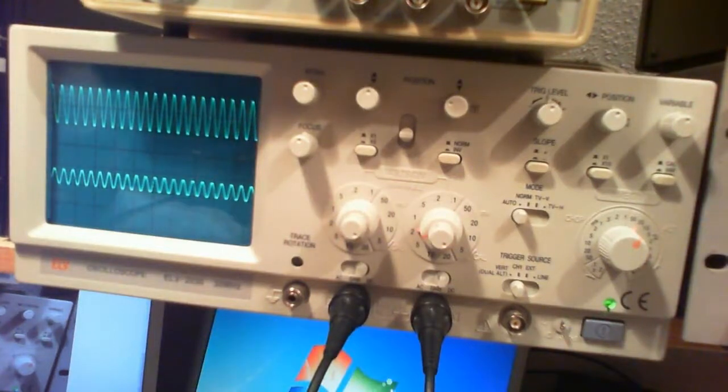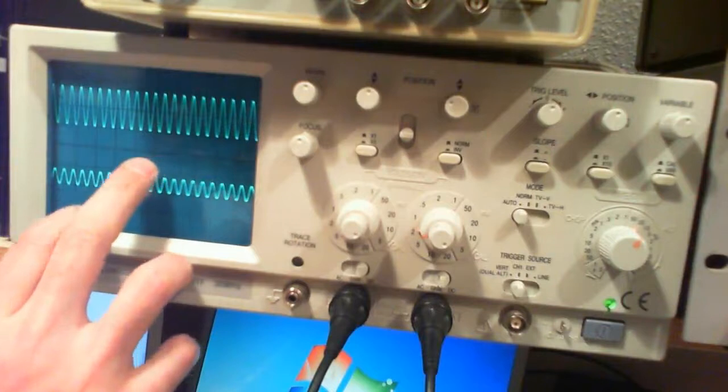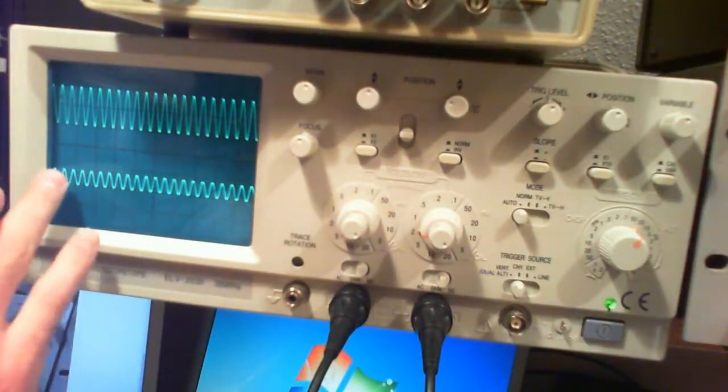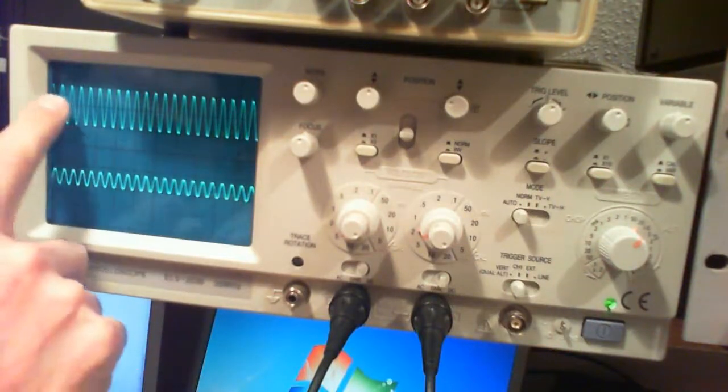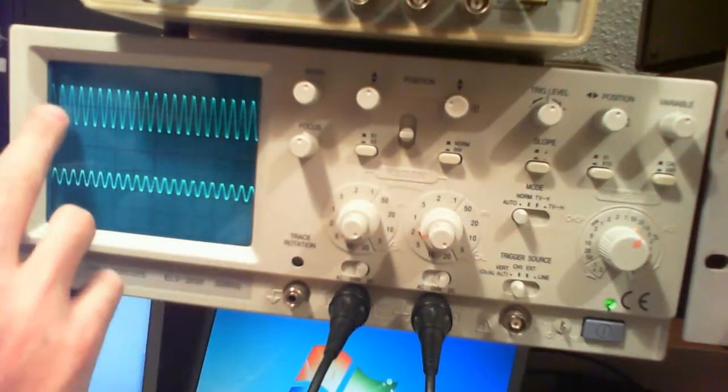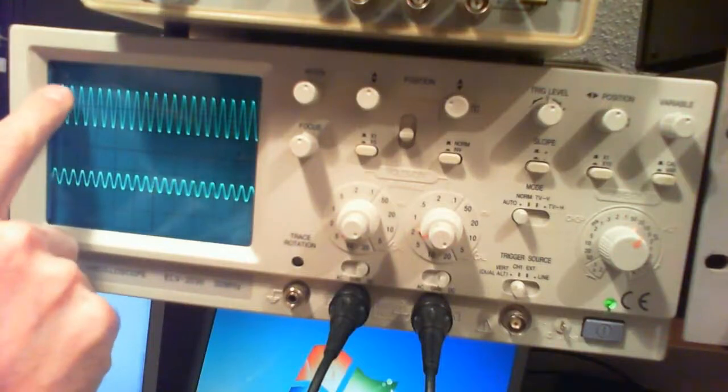Okay, so now in order to jot down some values for this circuit, I'm going to start at a very low frequency. You know that this circuit is actually kind of like a low pass filter, meaning that at very low frequencies it's going to give you a high voltage, and then the voltage is going to come down, and the curve is going to be something like this.